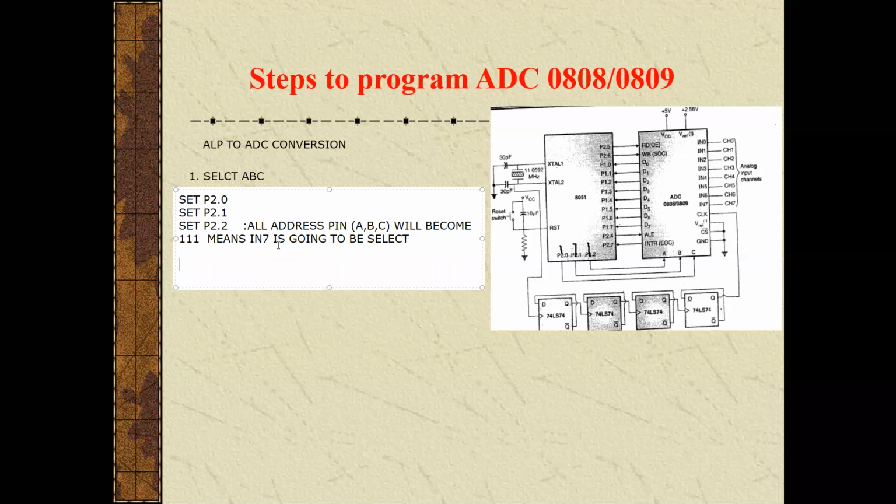Then after that we have to provide a low to high signal to this ALE. So what is the ALE bit, where is it connected? Here, this P2.4.